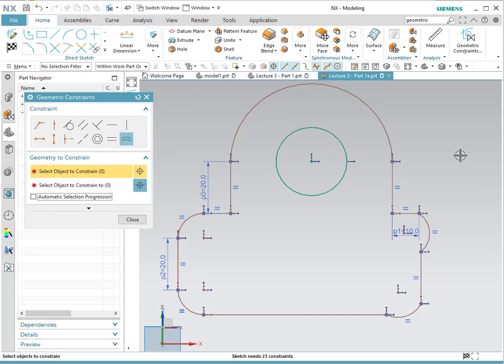notice that now what we see is that there is no tangent behavior between the lines, which is something that we needed. So we're going to go around and add it. This line is tangent to this. Notice that because I didn't remove the automatics, it did the wrong selection. So we're going to undo, click it, because we only needed two.